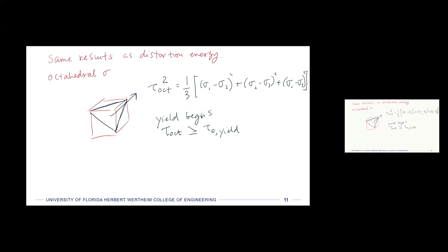So we've been going back to all of these uniaxial tension tests. Right? And so we can go through sort of a similar procedure where we would, in a tension test, define the octahedral shear stress if we only had sigma 1. Right, which comes out to be square root of 2 divided by 3 times the yield stress.